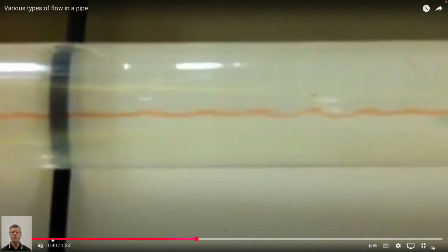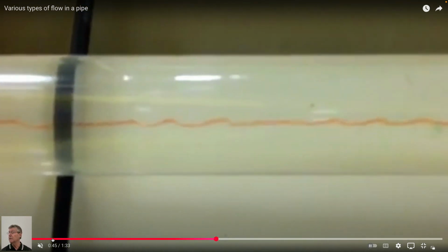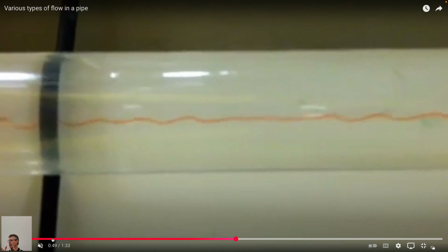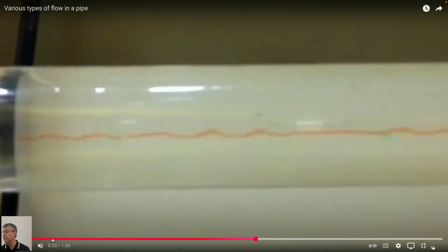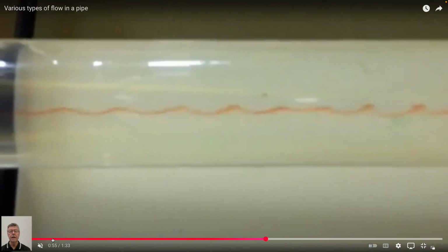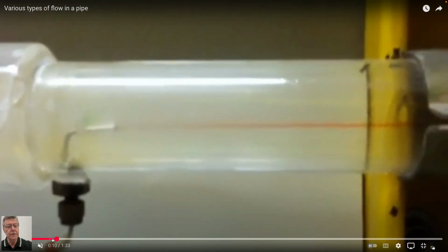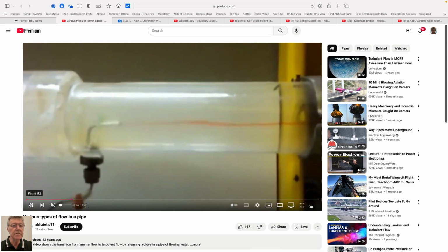And sometimes you don't want turbulent flow if you're going along, and often you want it. We talked about the golf ball with dimples on it. The dimples are to make the boundary layer break up as turbulent flow, and so there's less drag, surprisingly enough, if you have turbulent flow. And so the golf ball, for a given impulse of force that you apply, will go further. And so that's the whole reason for doing that. And so that's kind of what we'll deal with today. So that's that.